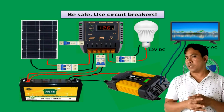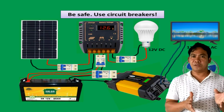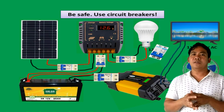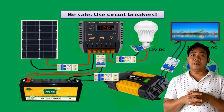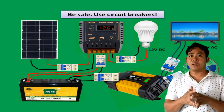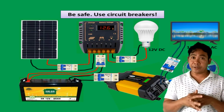And in your inverter, you can also put a circuit breaker. On that side, these circuit breakers are DC circuit breakers. On the AC side, from the output of the inverter, you should install AC circuit breakers.